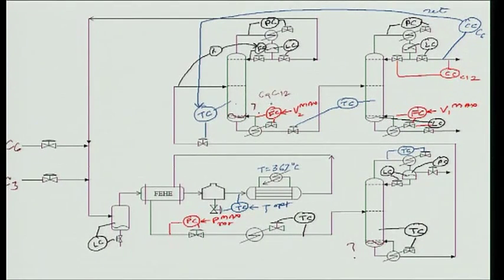C9 and C12 are essentially reaction products, and if this level is increasing, it means I am producing too much C9, C12 in the reactor, which is accumulating in the column bottom. So I need to reduce the ethylene to reduce the amount of C9 and C12 formed in the reactor, so that this level may go back. Yeah, that makes sense.